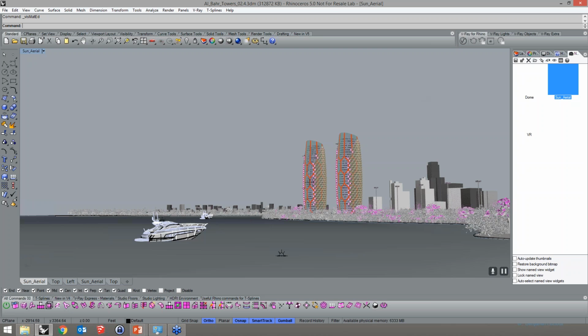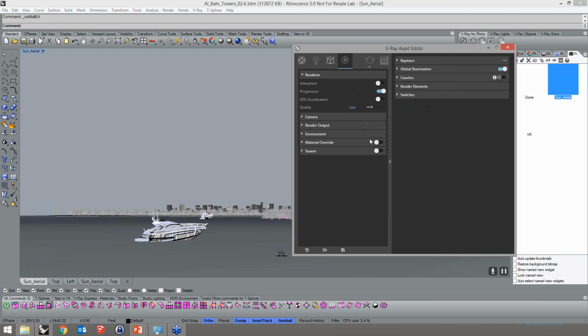Does the swarm rendering use only CPU rendering, or does GPU rendering work? Either one works. Whichever one you have enabled here is what it'll use. So if you have GPU enabled, then Swarm will seek out machines that have CUDA enabled GPUs and will use them as well. And if you use two video cards, can you use GPU optimization separately, one for the program and one for the renderer?